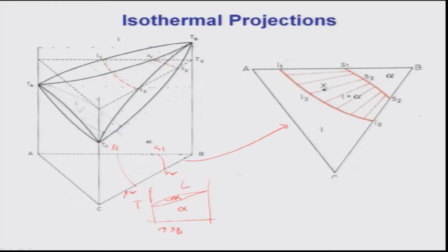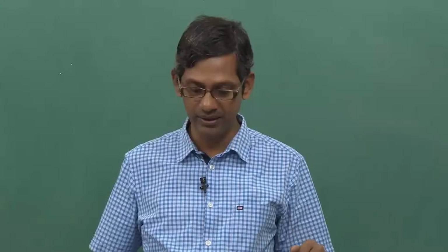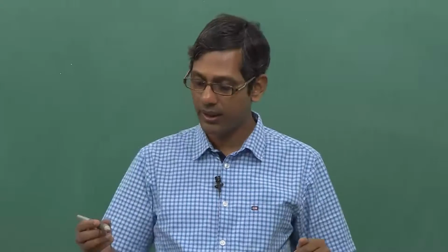Okay. So, in the 3-dimensional model we have two surfaces, one is the liquidus, the other one is the solidus. Now, we can use this to understand the solidification pathways, how an alloy will solidify. Please remember, I have done it for binary, so I will do it for binary again first and then discuss the ternary, correct.